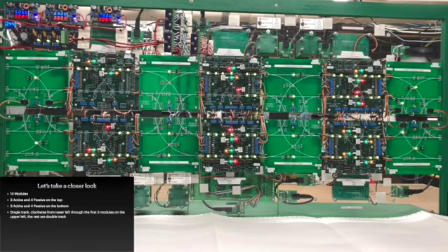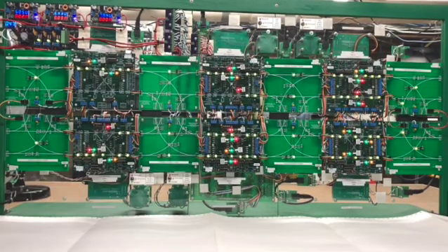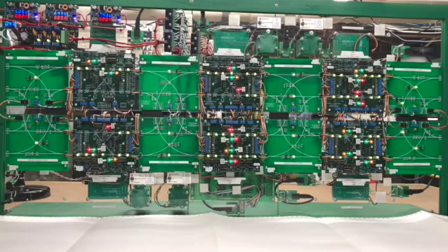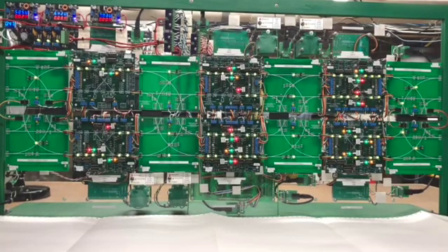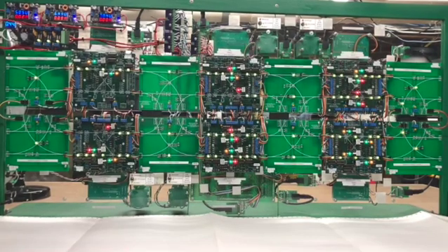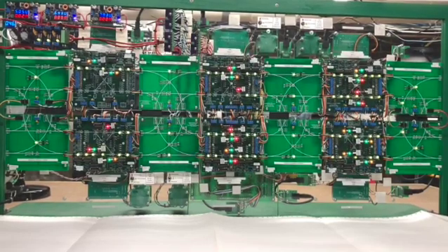It's a single track on the first 3 modules in the upper left corner, and the first module on the lower left. Everywhere else, it's double track. For each track segment, the LEDs indicate red for occupied and green for unoccupied. There are only 2 types of signal heads used, a single-headed dwarf and a double-headed mast. Each signal is facing the direction of the train it's supposed to control, which you can tell by the white squares on the base of each signal. I should note that if you see a 2-headed signal that is indicating red over nothing, the lower head is supposed to be a flashing yellow. I had a bug in the signal definitions when we filmed this, which has been subsequently fixed.